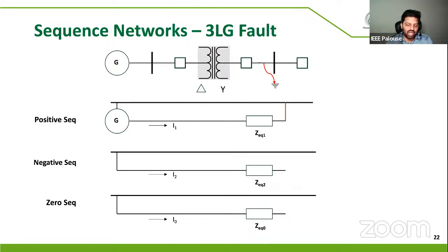So when we have a fault, our interest is to identify the fault current and also look at these three different sequence components to understand what kind of fault it is. All these calculations happen in real time in production devices, which make the decisions and protect the system.